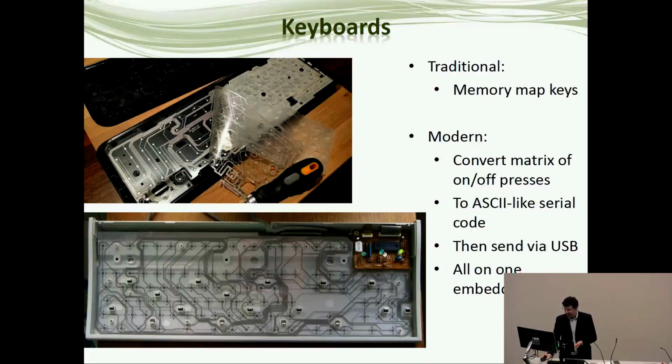You can see there's a whole chip inside your keyboard. So there's a small embedded computer in your keyboard. This is looking for those presses coming in. It's going to translate them into an ASCII-like serial encoding, and it's going to convert them to USB messages. There's a whole load of work you do to read and write the USB protocol, and it's going to stream those out over USB. The advantage of that is you get this standardized I/O.